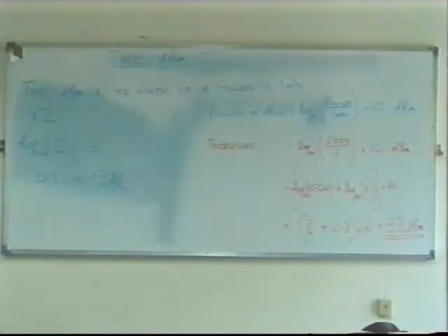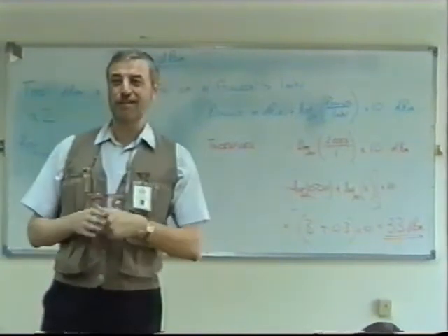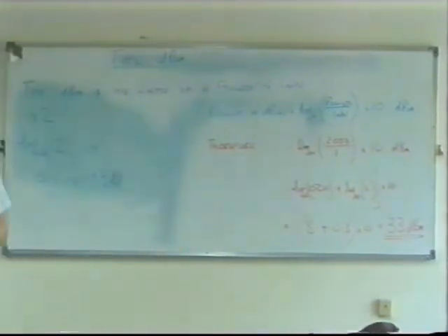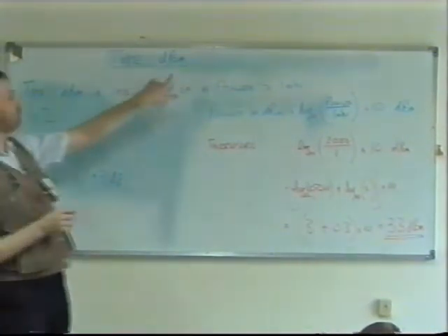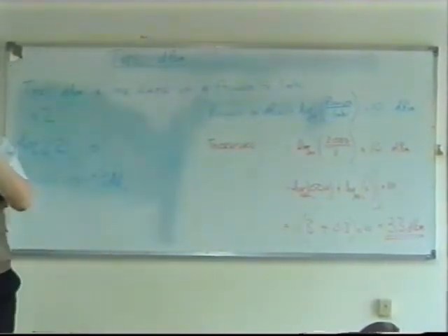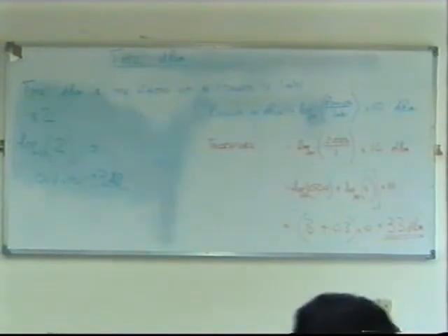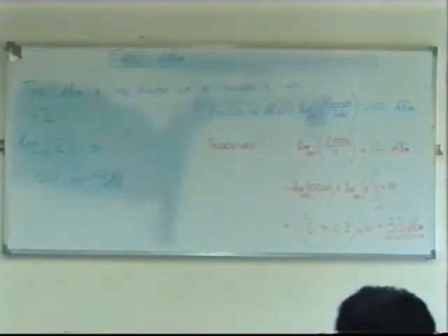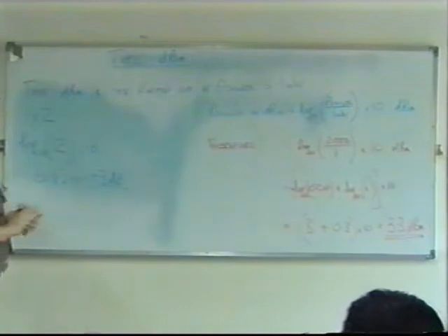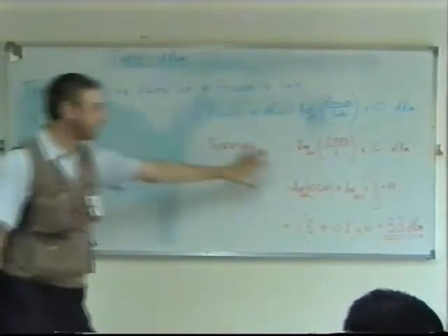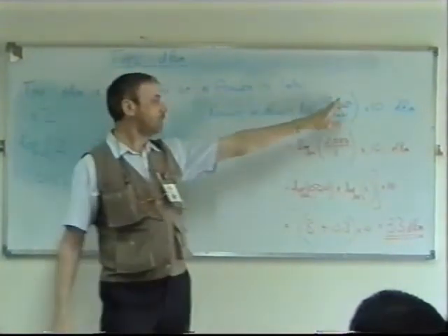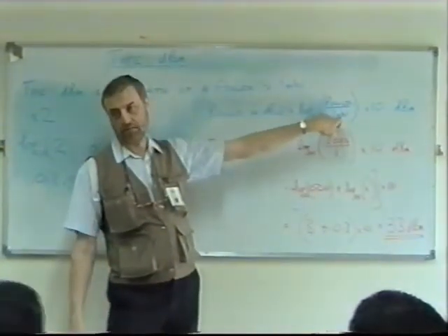Anyway, whether we like it or not, we've still got to measure our power ratios in decibels and, for small signal powers, in dBm. This is true for when we're talking about radio as well as telephone and modem circuits, they use the dBm. So the way we use the calculation is the same, except with dBm, it's always relative to 1 milliwatt.